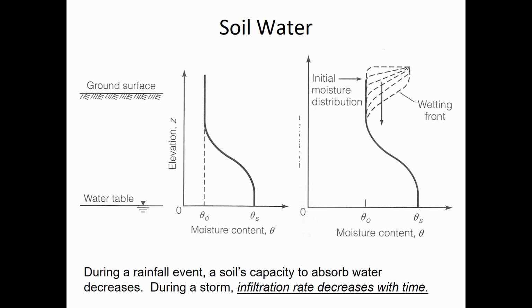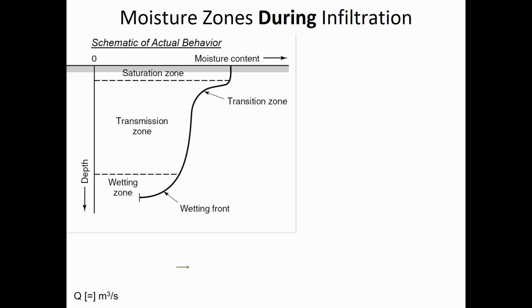The initial driving force, what we saw at first in those videos, is that the water penetrated downward and sideways very quickly because there was a lot of suction. But then as more of the grains become filled, there's a smaller driving force, because that suction or tension head decreases. Okay, so this is what happens during infiltration.